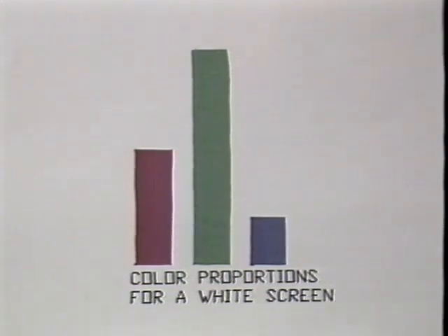This involves reducing the gain of the red and blue output transistors so that they only cause red and blue phosphors to glow as brightly as the green phosphor does when it is driven full strength. As you can tell from the description above, each color of phosphor has a different degree of luminescence or brightness, and the green phosphor is the dimmest of all. If all 3 phosphors were allowed to glow as brightly as possible, the color balance would be incorrect.